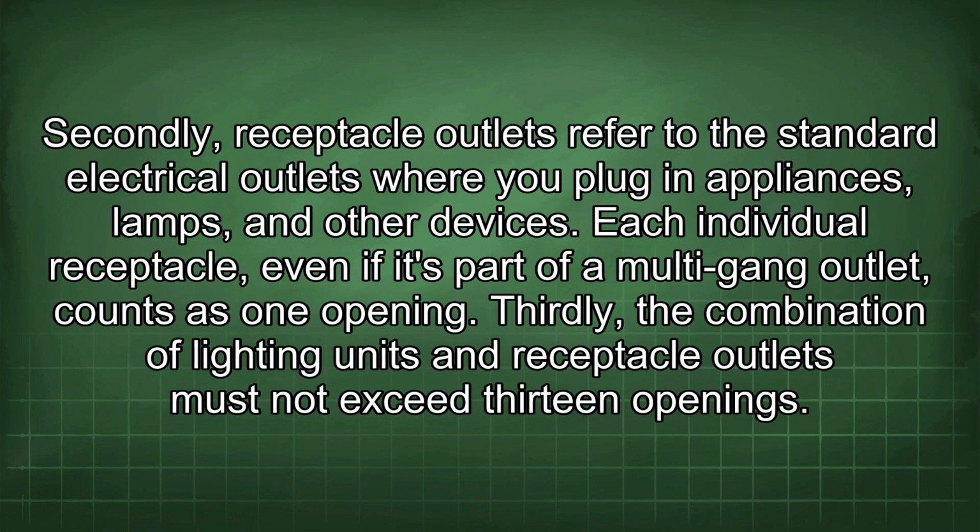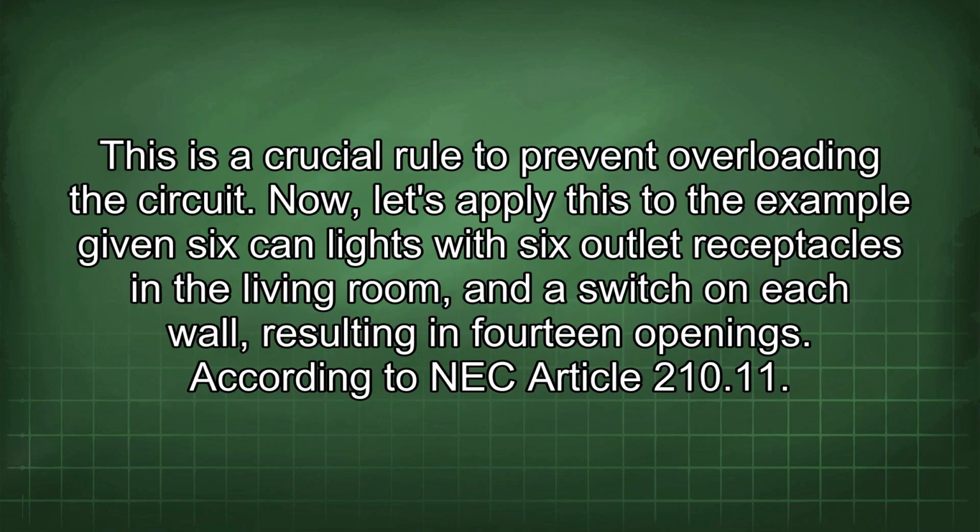Secondly, receptacle outlets refer to the standard electrical outlets where you plug in appliances, lamps, and other devices. Each individual receptacle, even if it's part of a multi-gang outlet, counts as one opening. Thirdly, the combination of lighting units and receptacle outlets must not exceed 13 openings. This is a crucial rule to prevent overloading the circuit.